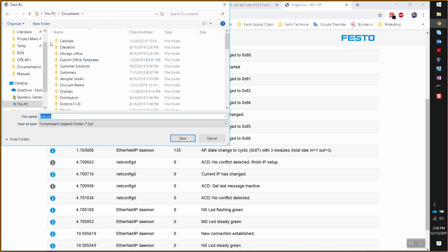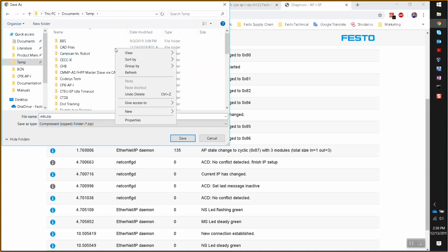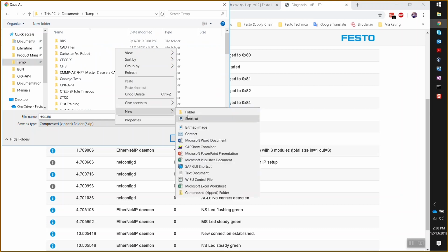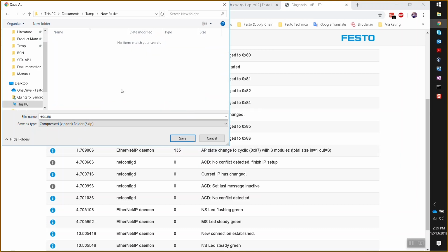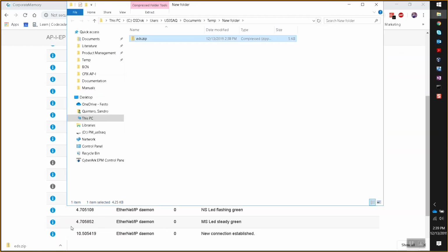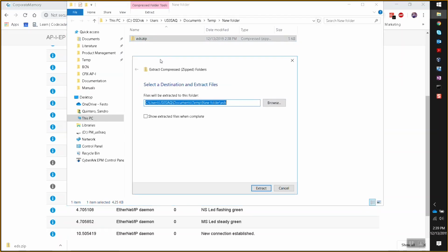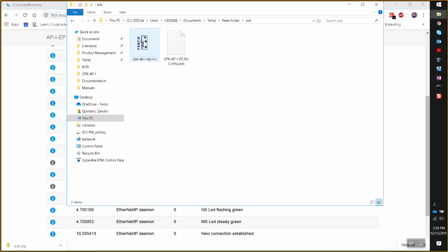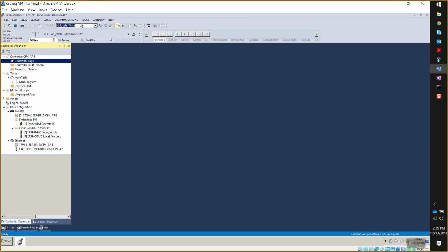Okay, so yeah, that's good. So you can save that EDS file, and this would give you a benefit of having the device shown in the list of the Rockwell system, and you could use what's called an EDS AOP for configuration. So I think it becomes a cleaner look when you do your configuration. Right. So now I have the icon and everything. Okay. I guess they give you a better user experience. Yeah, I mean, this is what I do with any other device, right? So basically, the first thing that I have to do is register that EDS, right?